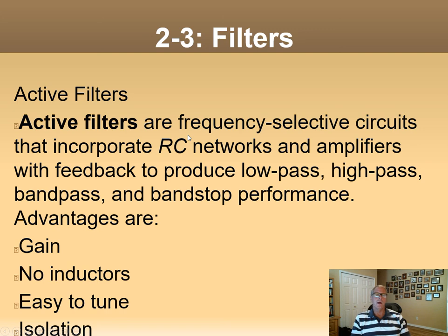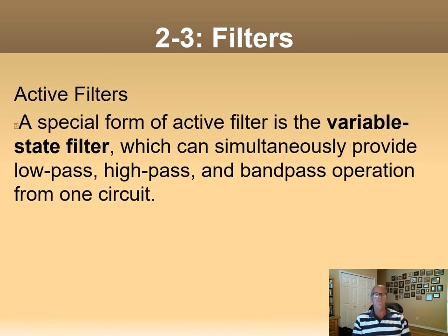Now, active filters, usually we make these out of op amps. The follow-on to our semiconductors class is integrated circuits, which is taught in the spring, and we do active filters in that. Unlike the passive filters that we've been looking at, you can add gain to them. There's no inductors. They're easy to tune, and you can provide isolation. So it's kind of a big deal. Variable state filter, we look at these in integrated circuits. You can do high pass, low pass, and band pass operation in one circuit. And you can make all those different filter topologies. You can make Butterworth and Chebyshev and Bessel and all those.